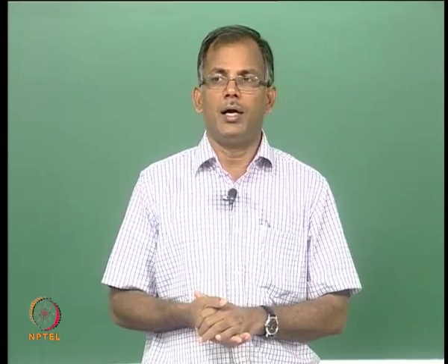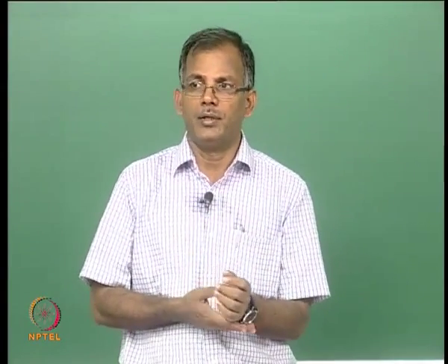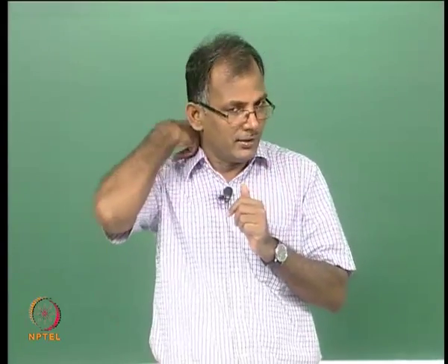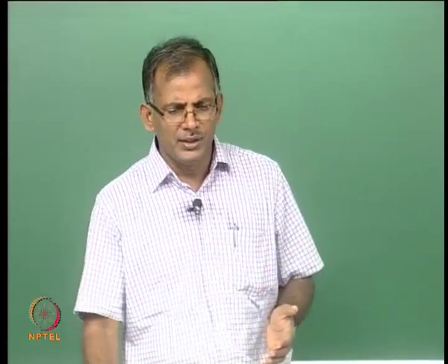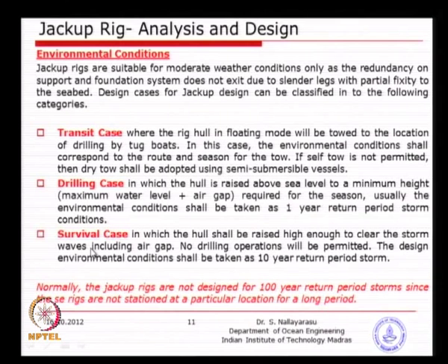So, you will select a window period by which you will have control over the period which you want to tow. Unless you have a job in a particular country, you need to go there at a particular time, then you have no choice. But you will design and verify the jackup within the limits of what was originally designed, unless it is designed for such a small sea state, then it may not be suitable. In many cases, when you have designed for the survival case, automatically it will qualify for a larger sea state for transit, which I think is inherent in the design.